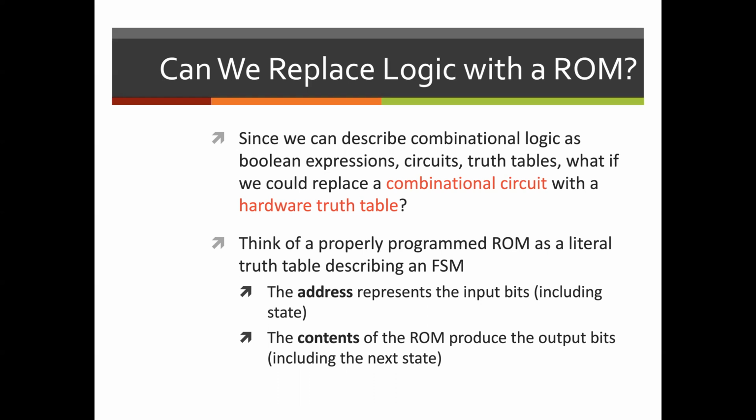And so if we were to take into consideration, if you have 72 controls in our data path, then we would have 72 bits in our output. And so there are a few steps that we can keep in mind to do this. We can create a state transition table, decide how many flip-flops we need and what kind, and use the flip-flop excitation table to determine the next steps for implementation.